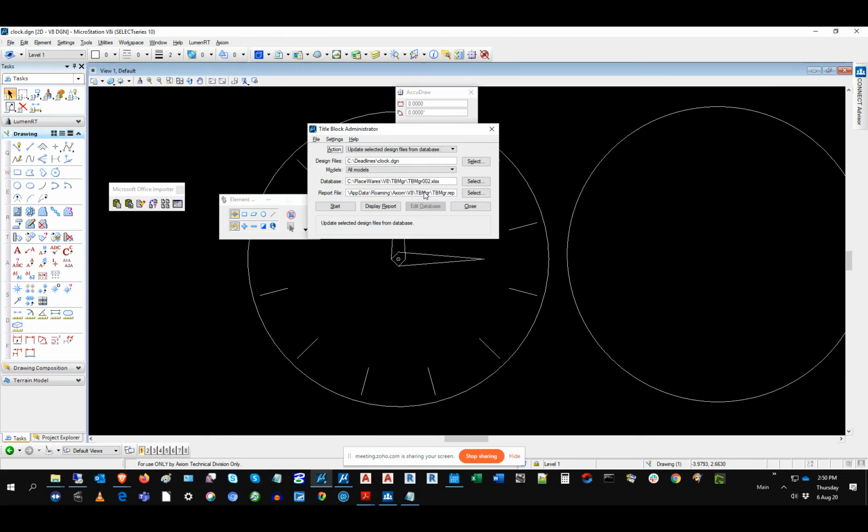If you have, and this is less common than it used to be, title blocks that are in regular cell, simple cell, shared cell, or simple text elements, you can also use a special tool called Upgrade Existing Text to Title Block Manager Text to set up rules in order to recognize things like the sheet numbers, sheet totals, etc., in your design files.